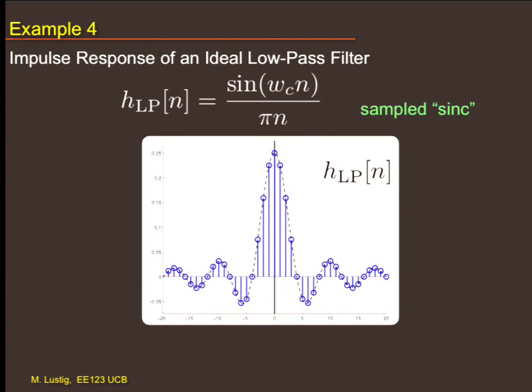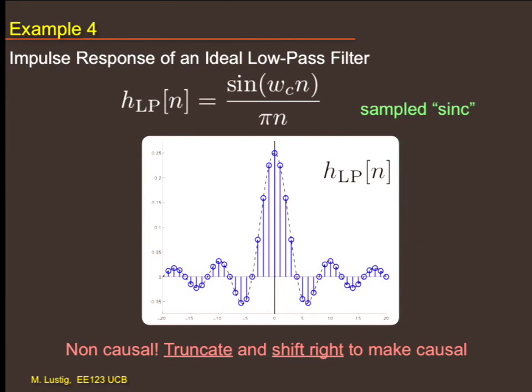That's great. Now, let's say I want to implement this ideal low-pass filter. It's not possible, but I want to do something about it, so I'm going to approximate it. One way to approximate this filter is to, first of all, truncate it, because I cannot do that infinitely. And then in order to make it causal, I'm going to shift it such that its center is shifted away, but the edge of it is on 0.